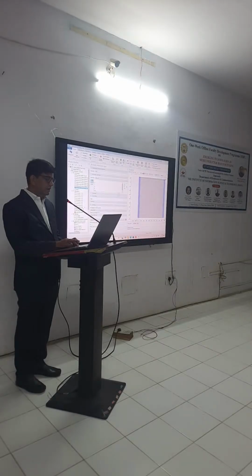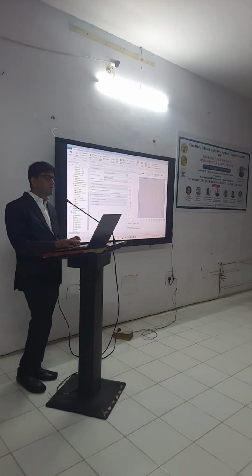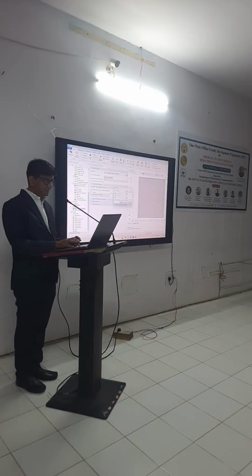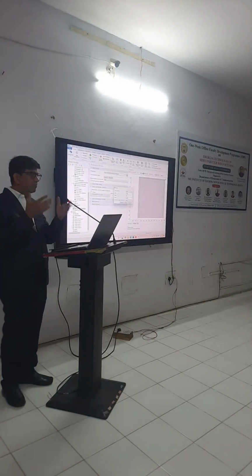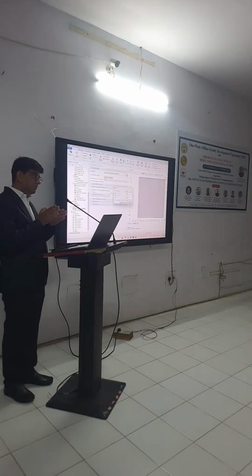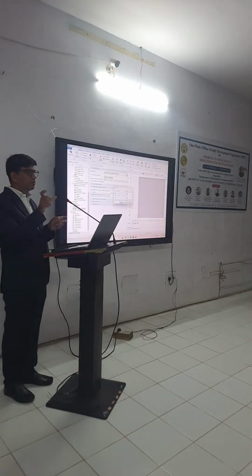After defining the PML layer, what I have to go for is analysis. For that, I am going to study. What kind of study did I select? I selected frequency domain analysis. In this frequency domain analysis, what do I need to do? I have to provide the frequency range. In this frequency range, you want to perform your analysis over your device, because you know the resonant frequency of your device. So it should be selected. For example, your resonant frequency is 2.4 GHz. So you have to select a frequency range between 2 to 3 GHz.